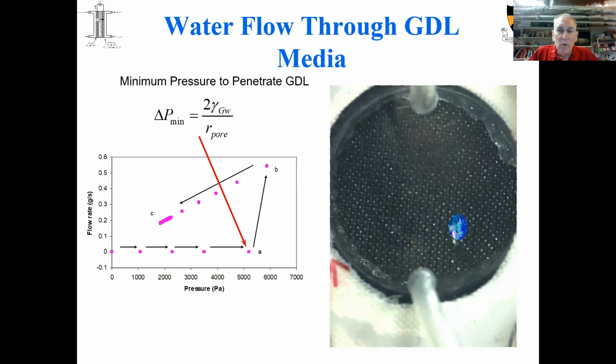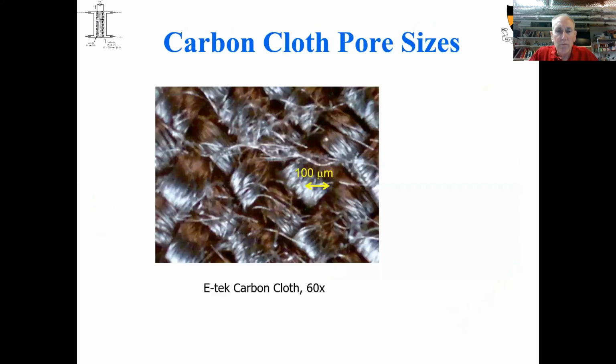And we then realized what was happening was that these porous carbon materials are hydrophobic. And so the water doesn't want to go through them, and the water looks for the path of least resistance, which is the largest pore. So contrary to what was thought, the water goes through the largest pore, and the gases go through the smallest pore. We could even tell where these pores are.